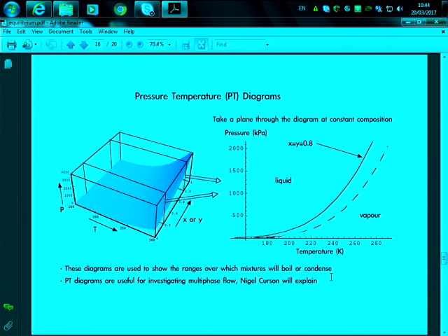Bubble flow, chunk flow. Okay? And what are those flows dependent on? On the velocity of the gas and the velocity of the liquid going through the system, and also on the fraction of gas and liquid, because the velocity is basically the mass flow of gas and the mass flow of liquid. So if you have mass transfer happening and the masses are changing, you may change from a bubble flow to a different flow throughout the pipeline, changing the entire pressure drop, which complicates the whole system.